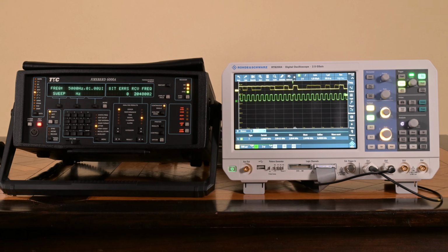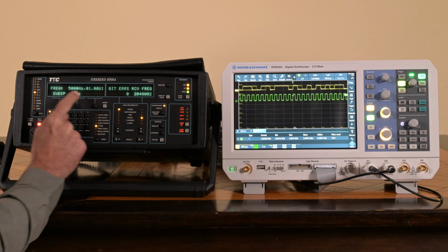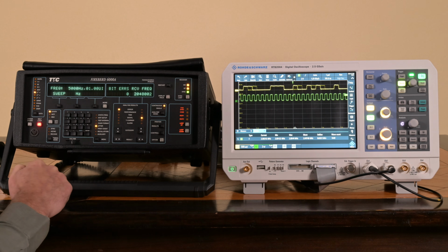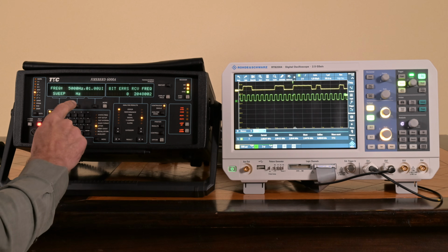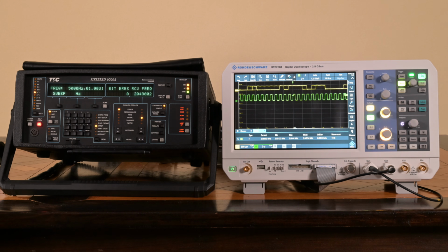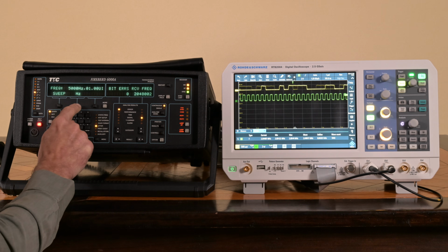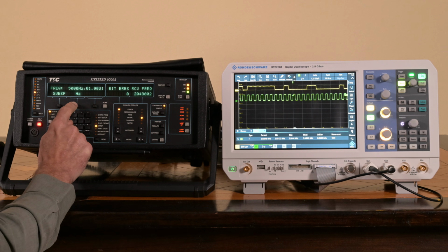And the frequency is kind of the most important setting. That's the amount of jitter that has been added to the clock signal. You can either have it sweeping or you can set it in hertz. So you see now that it is set at 5 kilohertz of added jitter. And the jitter, as I already noted, is quite visible but not leading yet to bit errors.